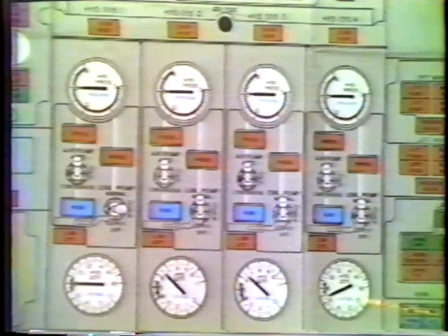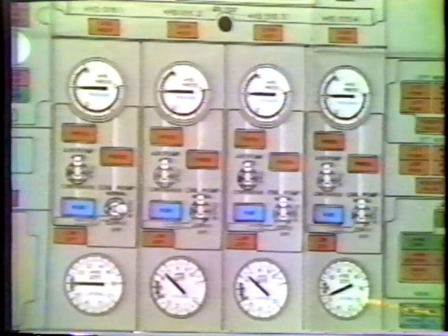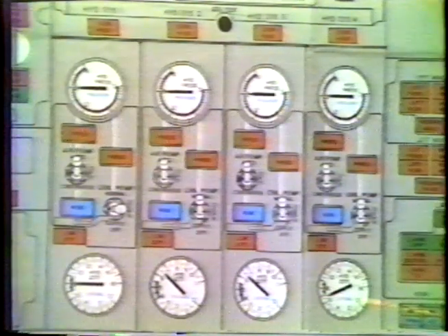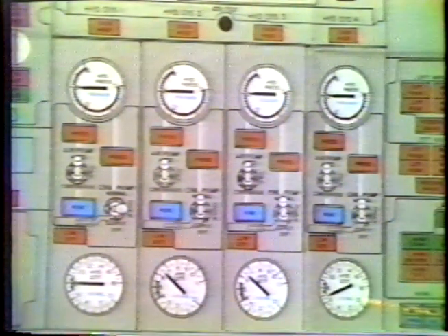So if a quantity light comes on and the pointer looks good, the first thing you ought to do is see if the quantity test gauge works. If it doesn't work, then you better believe you have low quantity and take the appropriate action.